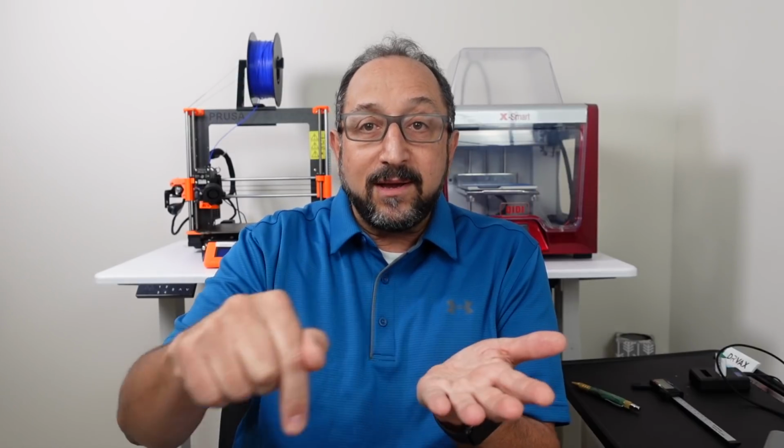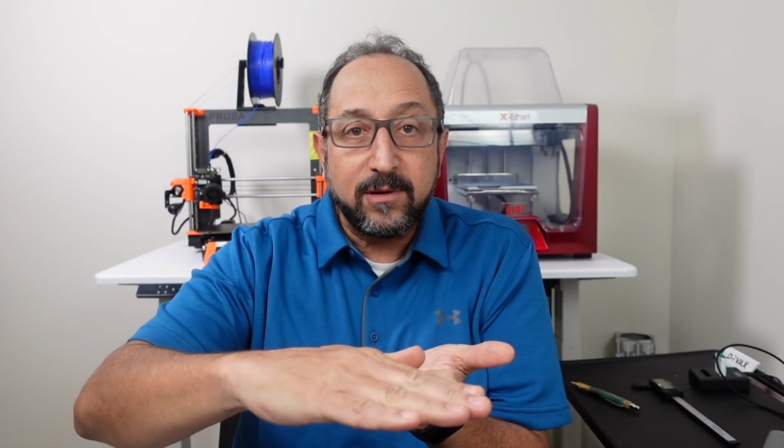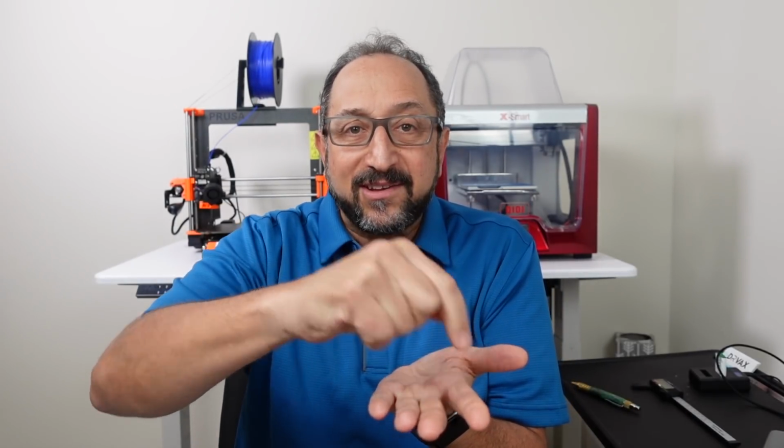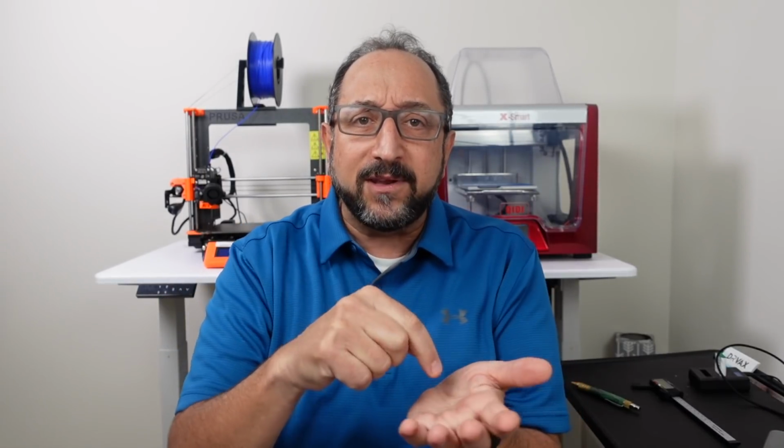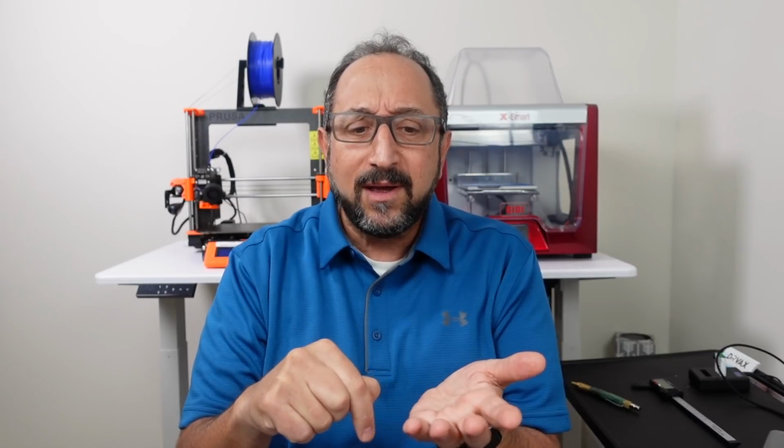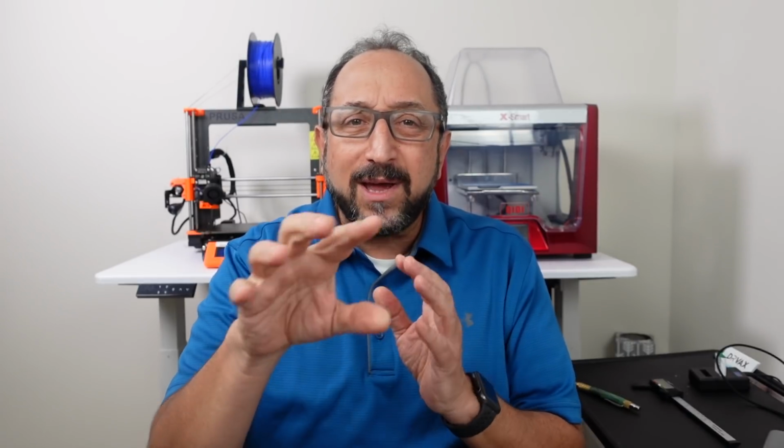When you're printing, in essence, you've taken the triangles that are created in your STL file and defined them into layers. And so in essence, a print is not a series of dots. It's really a series of segments. The smallest segment that you'll attempt to print is the resolution. If you have that too small, then you'll get more bumps and artifacts in your print.